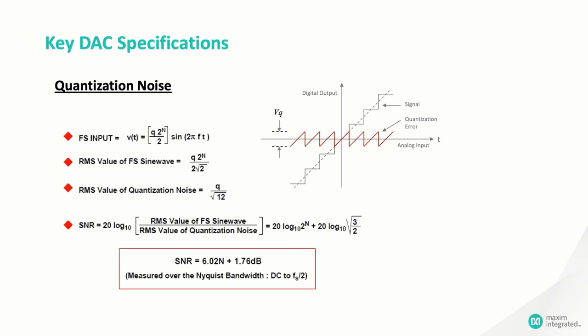But we're not just sampling, we're also restricting the output signal to a set of predetermined levels in a process called quantization. And that process introduces a form of distortion known as quantization error. The noise component in the output signal is called quantization noise. Now, the good news is that just like Nyquist's law tells you how fast you have to sample to reproduce a particular frequency, there's also a rule that tells you how much quantization noise to expect.